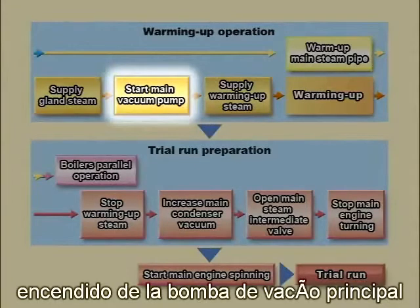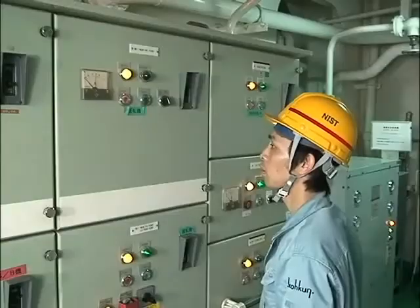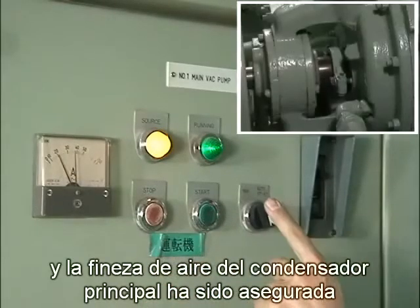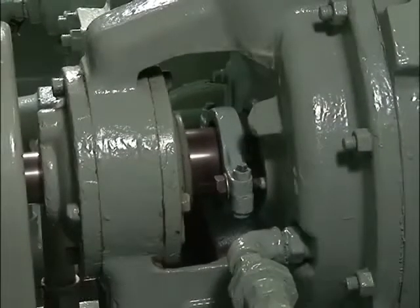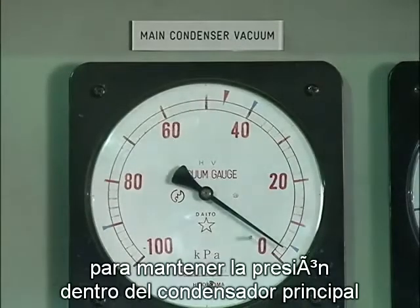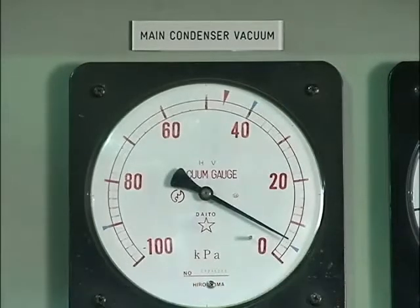Start main vacuum pump. Once gland steam has been supplied and air tightness of the main condenser has been secured, start the main vacuum pump. Then repeat pump starting and stopping intermittently to keep the pressure inside the main condenser lower than the atmosphere.